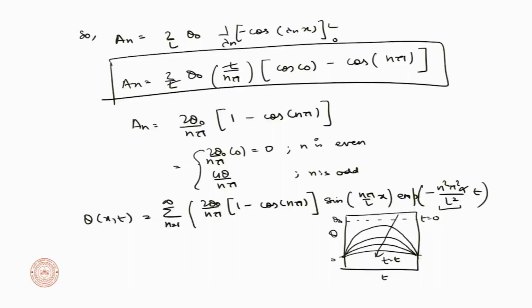Okay, we'll go into non-dimensionalization. Again, let's take a system. Let's take a box. The temperature over here is T of x comma t. We have our domain x equals 0 and x equals L. We have an ambient as T infinity. This has properties: we have a thermal conductivity, we have density, we have specific heat. Let's consider a 1D system.